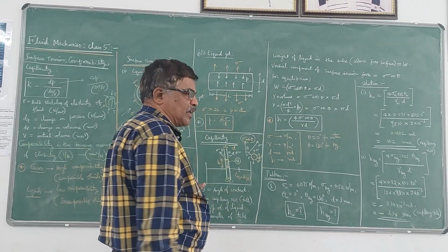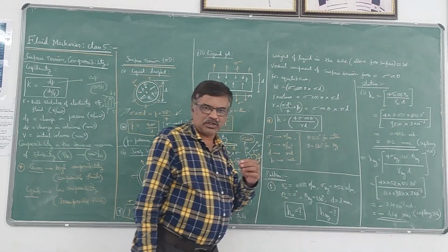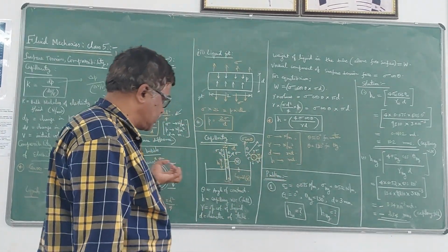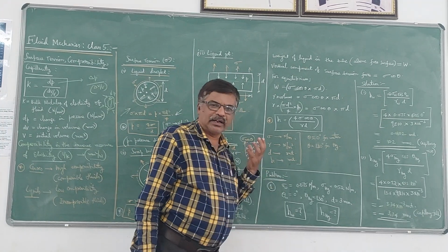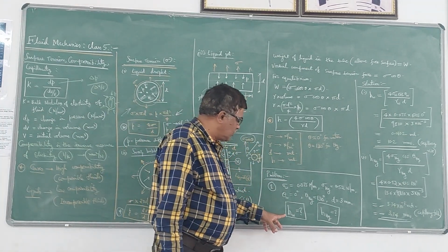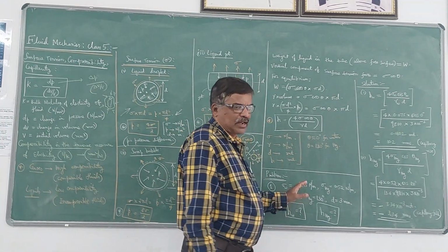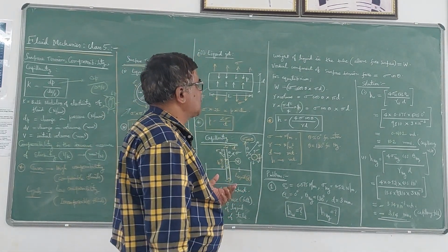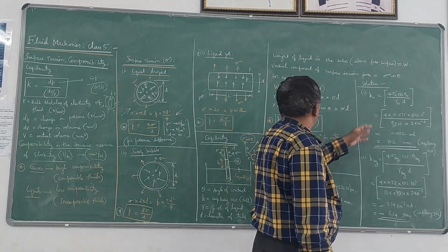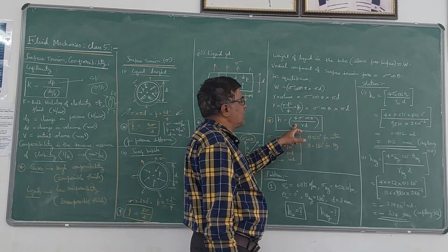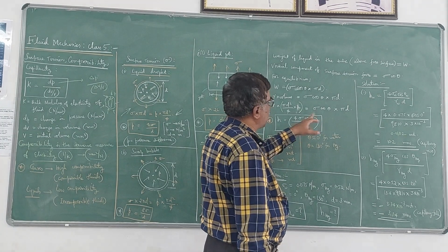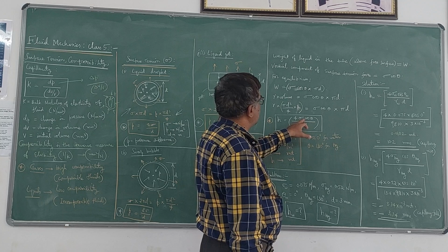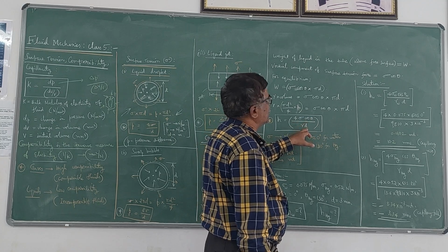So this process you can observe in roots of plants, where through those capillary tubes which are present in the roots, water will be taken for the plant growth. Now I want to find the value of capillary rise or capillary fall, whatever it is there for this data. So the solution runs like this. So I am going to use this formula directly. First of all, I will take that the liquid is water. HW I want to calculate. Liquid is water there. 4 sigma W cos theta W by gamma W into D.